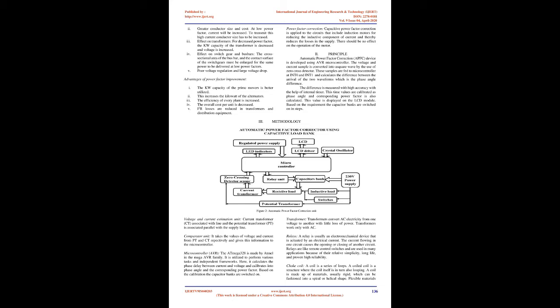Low power factor is due to inductive loads. Inductive loads require current to create a magnetic field that produces the desired work. This results in an increase of reactive and apparent power and decreases the power factor, or efficiency, of a system. Inductive loads include transformers, induction motors, induction generators, and high-intensity discharge lighting. These loads constitute the distribution system. This increase in reactive power results in a large angle between kW and kVA, which further results in a decrease of power factor.